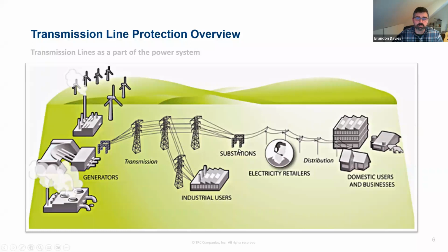down to another substation. This would be a transmission to distribution type station, where it would step down to a lower voltage and would go across the lower voltage distribution lines to get out to houses, businesses, industrial customers, things like that. There are some cases where you've got larger industrial facilities that have high power demands that would connect directly into the transmission system. But largely most of the customers to a utility are connecting in that sub-transmission or distribution type level.